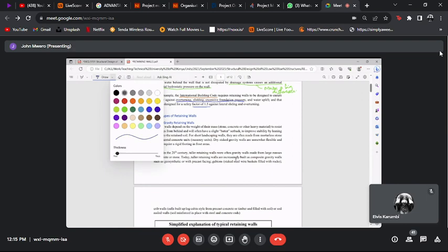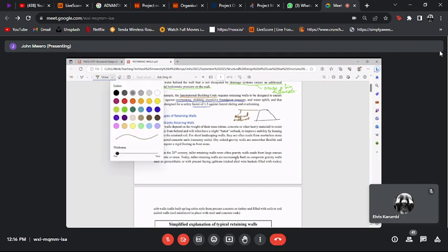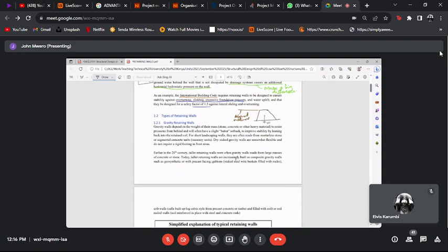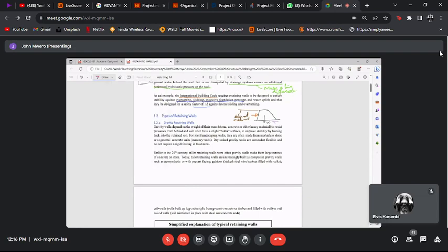So if you're doing a gravity retaining wall, you want a heavy mass. You want a big material. So this is retained material, and basically you have a weight here. And this material, of course, we've agreed that it's pushing that way. It's trying to cause this wall to move. So what is causing the wall not to move is basically that force there.